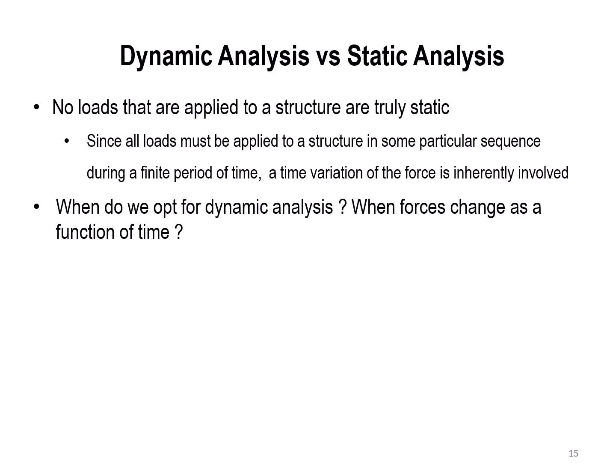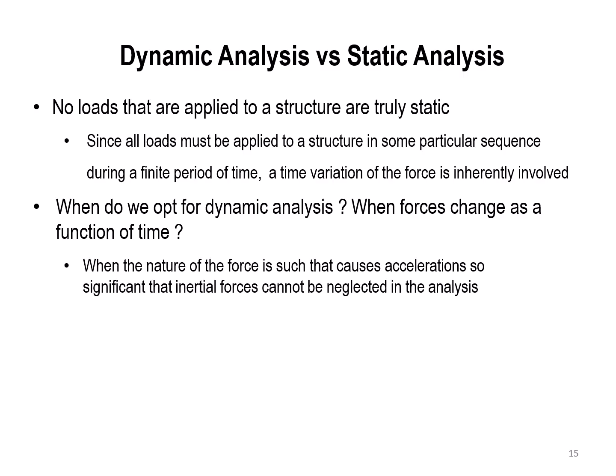So the question is, when do we opt for dynamic analysis, when the force changes as a function of time? When the nature of the force is such that the resulting acceleration is significant and the inertial forces cannot be neglected in the analysis, we need to apply dynamic analysis.